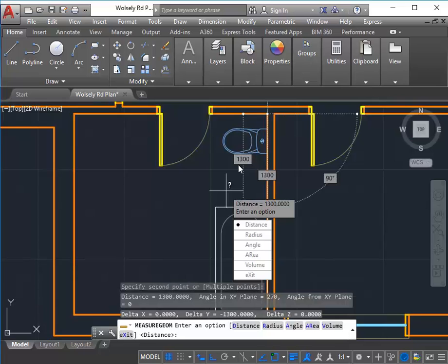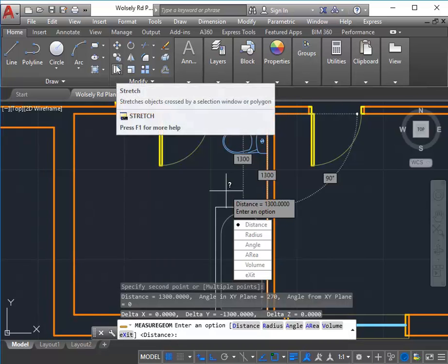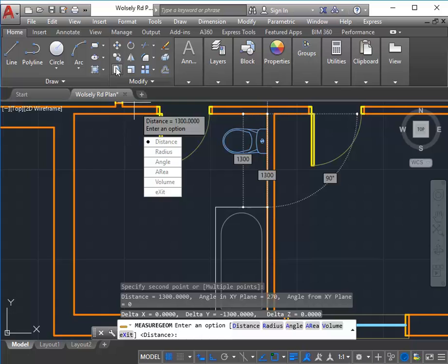A bit more. So from side to side, you probably want at least 800. No, from side to side. So from the two things either side of your toilet. So the space for your toilet should be about 800 at least. More would be good, but 800 is probably enough. At the moment I've got 1300, and that means that I can stretch this 500.